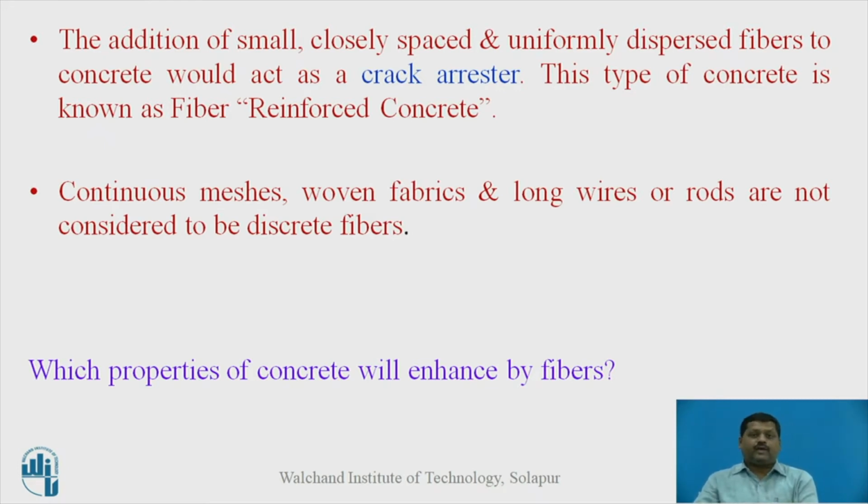Continuous meshes, woven fabrics and long wires are not fibers. Discrete fibers which are dispersed in the concrete are called fibers, and that concrete is called fiber reinforced concrete. Now, which properties of concrete will be enhanced by these fibers?